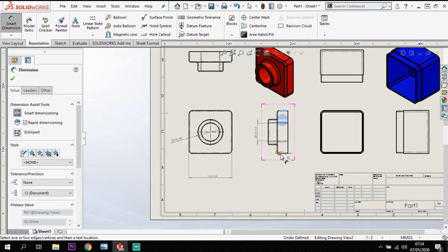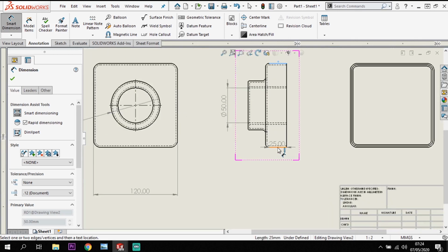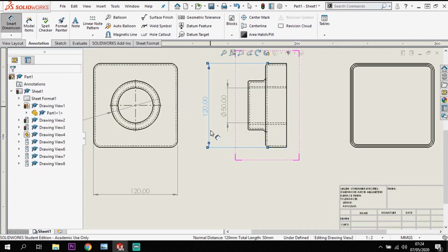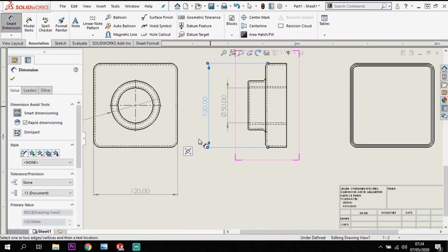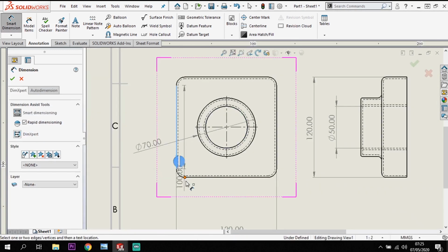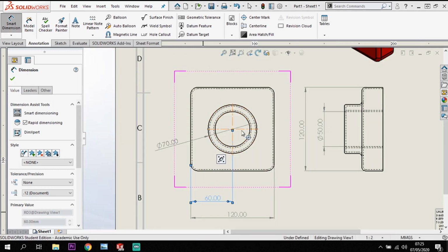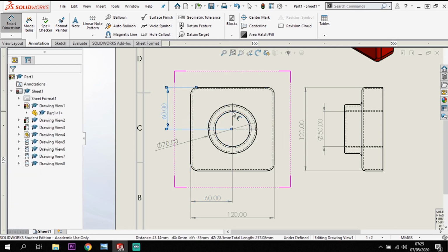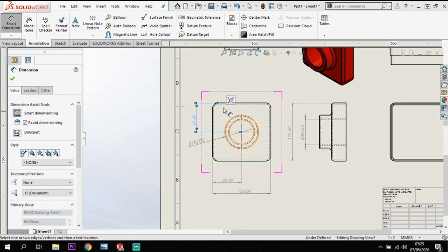Now with this, it gives me the option on this model to dimension up the full distance across, or up that height there, which is again 120, so we've got them two distance or dimensions on there. So we've got that centre point of that circle like so, coming down across the side, and then we can also work it coming from the top here, coming across there as well, to give us our position for where the centre of them two circles are going to go.